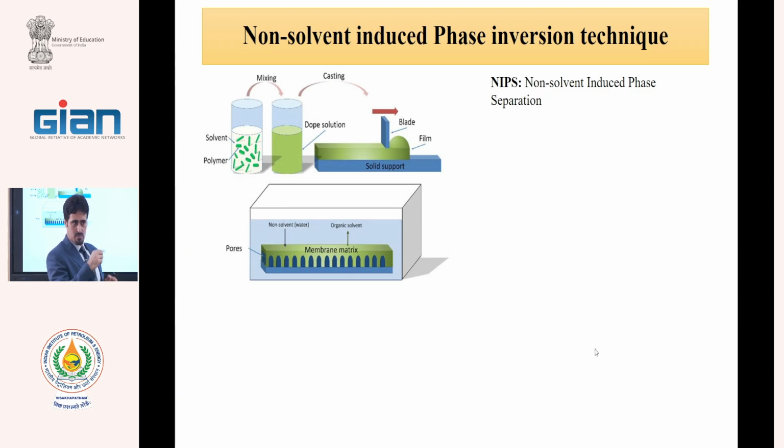Rapid exchange, small pores. If we have a slow exchange rate, we will have big pores. Okay? Therefore, with controlling of this speed, entrance and exit, that is called the exchange rate, we can control the pore size of the membrane. We can produce microfiltration if there is a slow exchange rate. For nanofiltration, we must increase the exchange rate.